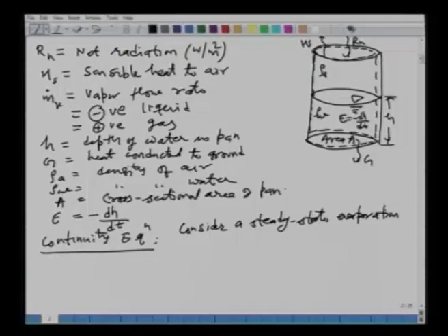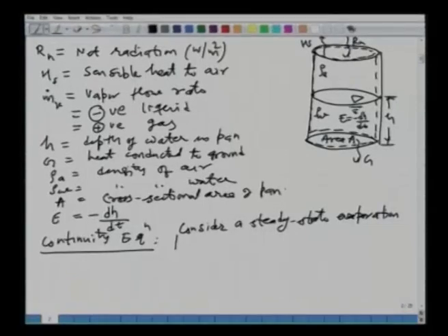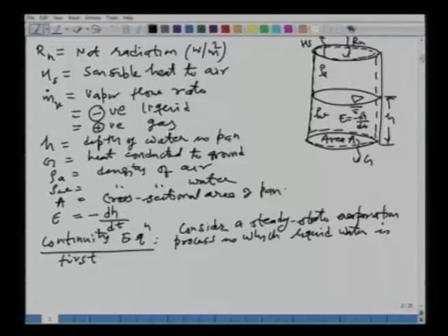This is important to understand, because the Reynolds transport theorem which we will write, we will have to take the different terms according to this assumption. So, we are considering a steady state evaporation process in which liquid water is first transformed into gaseous state, or I can say vapor, within the CV.